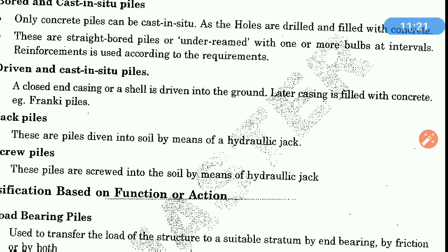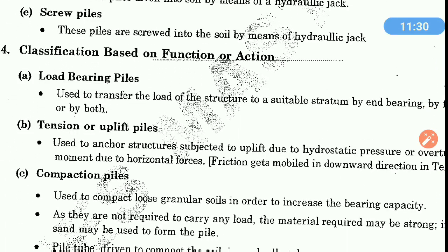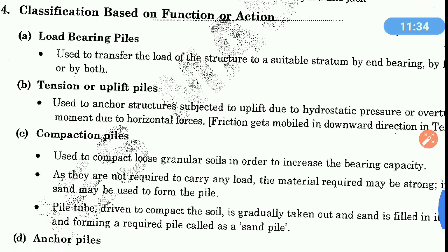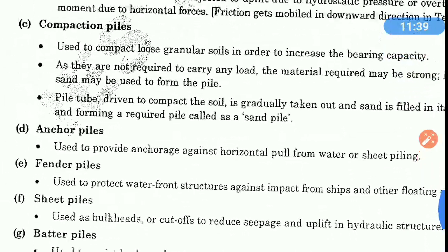And then the fifth one is screwed pile. These piles are screwed into soil by means of hydraulic jack. Classification based on function or action. On the basis of function or action, piles are divided into 7 categories,